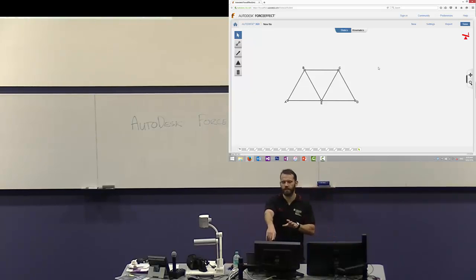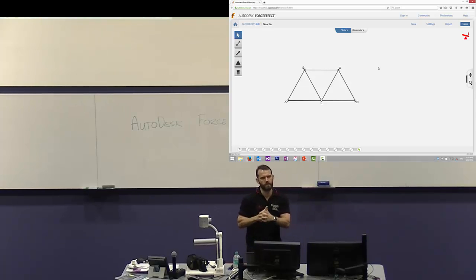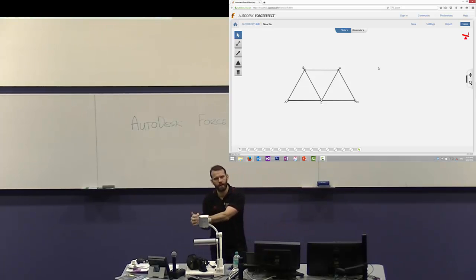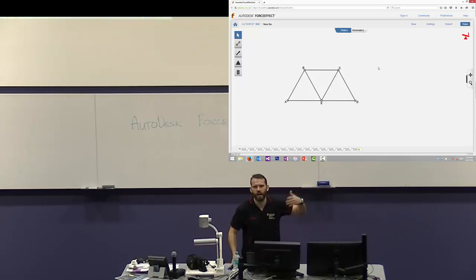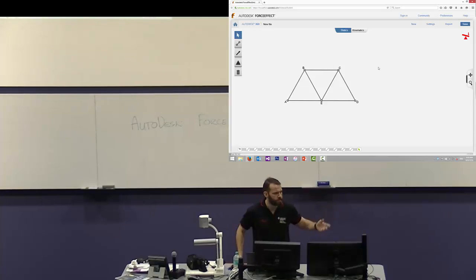Now, obviously, if you're doing this type of truss bridge or whatever it is, you'll have one of these on either side, right? So you're only really modelling half your bridge, and what we need to understand is that if we're applying a force to half the bridge, the force needs to be half the force we're actually applying. Yeah, because you've got half the structure, so half the force will give you the right constituent forces and so forth.